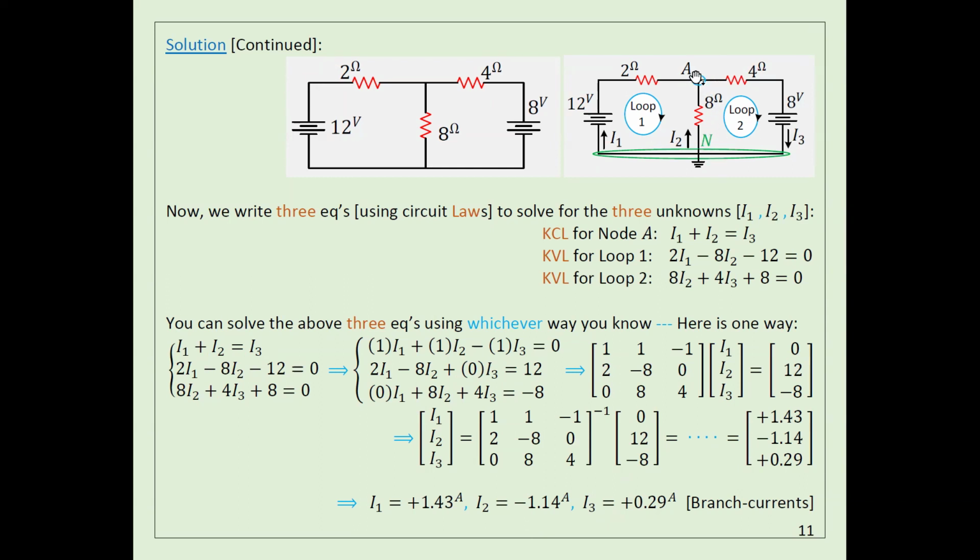So if you look at this node, you can see I1 enters, I2 goes out, and I3 goes out. You get what I'm saying? And if you add them, you will find Kirchhoff's current law is still true. Here you have I1 equal to I2 plus I3, for sure, if you ignore this negative, because negative means only direction. If you add this one plus this one, you get I1. So actually, I1 is coming this way, and then it's going to split. Some current is going to flow this way, some current is going to move this way. Any questions?